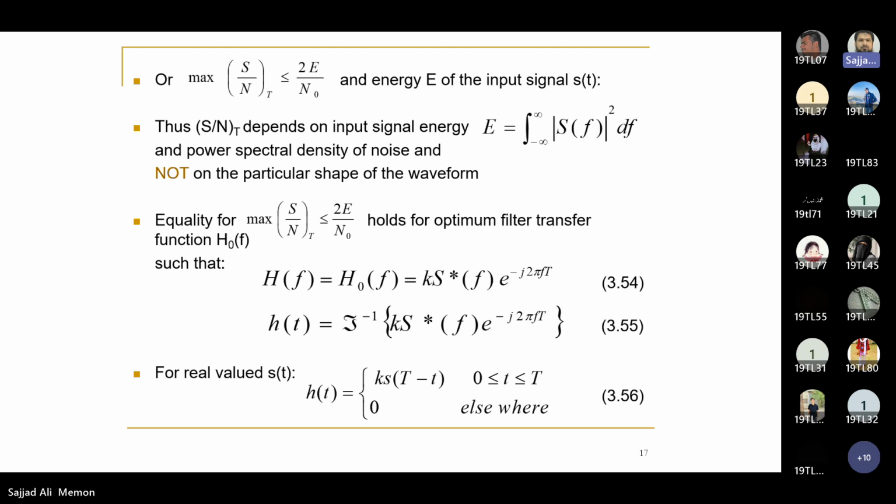Like we saw in the previous figure where we used the equalizer. The equalizer tried to fix the shape of the pulse, but even after passing through the equalizer, the shape of the pulse was not perfect. Still, it is very much understandable what values or what bits are being transmitted using that waveform. So the detection part, or step two, can easily understand from that sample what this sample is representing, whether it is a1 or whether it is a2.